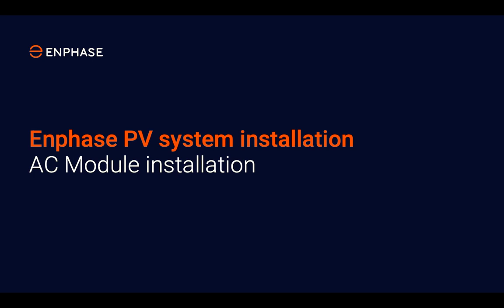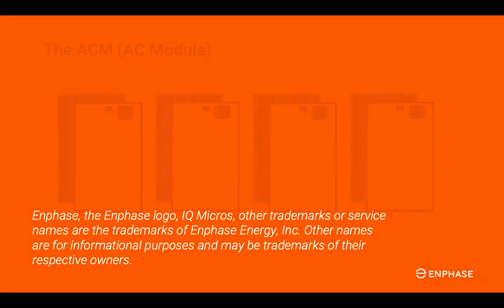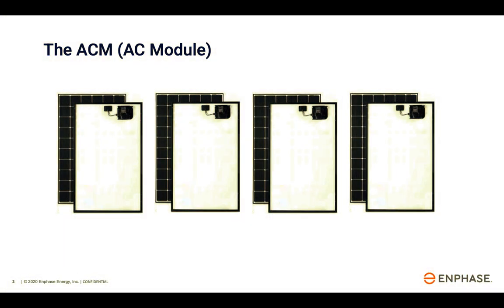In this lesson, you will learn the installation differences while using AC modules. Enphase has partnered with solar panel manufacturers to create a product called the AC module. AC modules, commonly known as ACM, are a microinverter and bracket that is attached to the backsheet of the module at the factory. This eliminates the need for the additional step of separately mounting the inverter to the PV array framing.